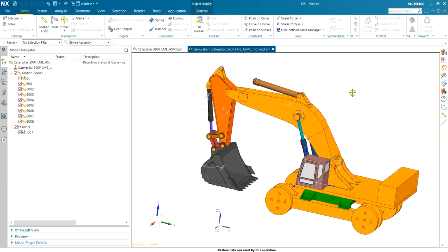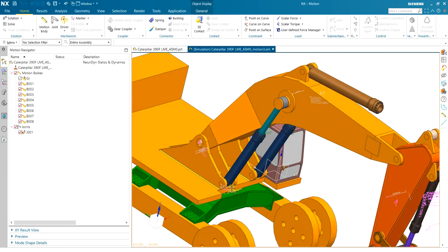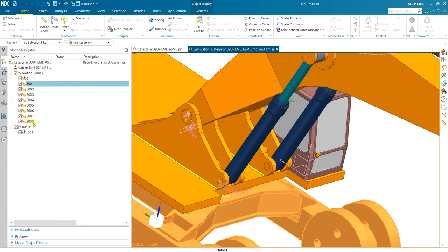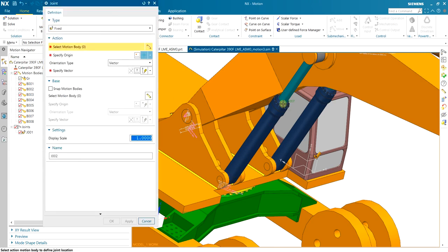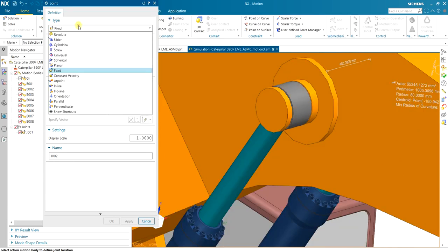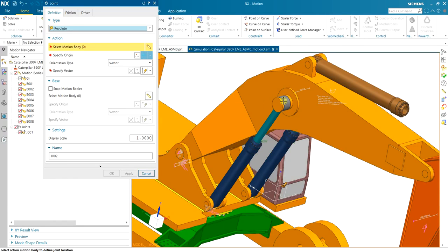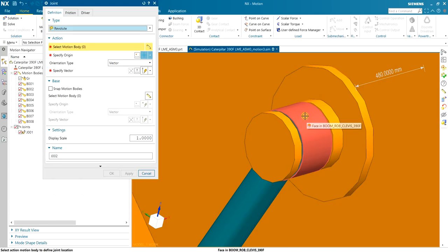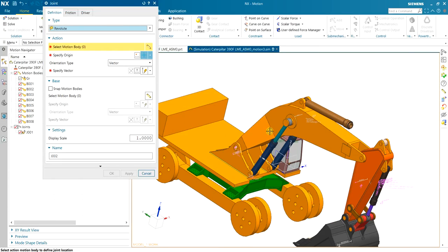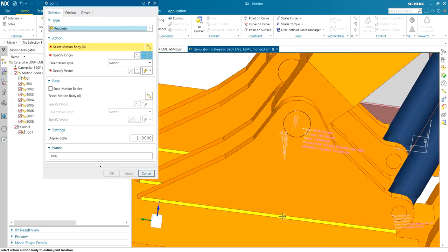We can move on to make the joint here, which we need, and here, and make a slider. First, the joint. We'll move to the joints. I want to have two joints on this piston and cylinder. The revolute joint. At this point, since we are not interested in the stress on this pin, we don't care about the exact location of the revolute pin, but we are more interested in the forces and stresses on the weld.